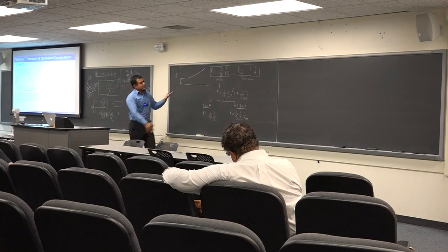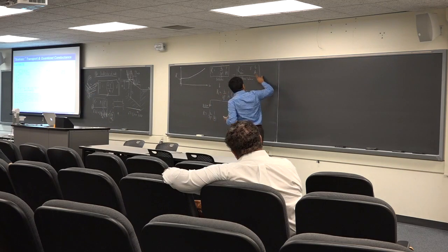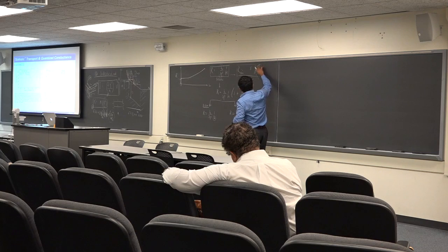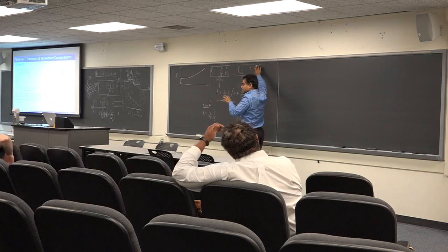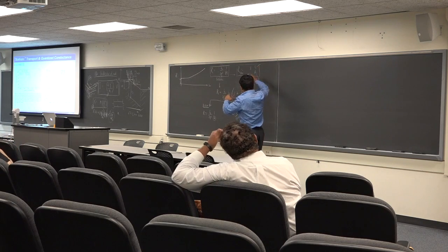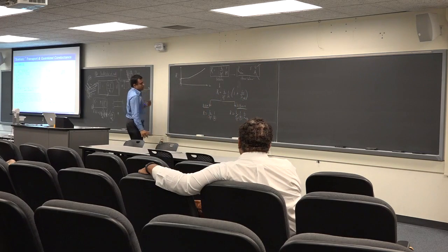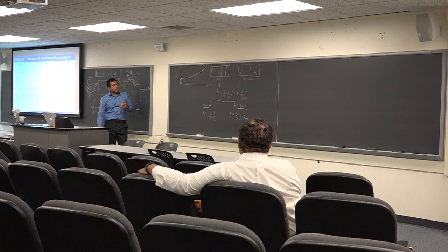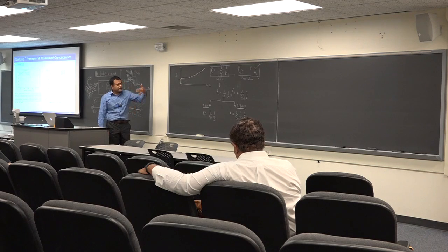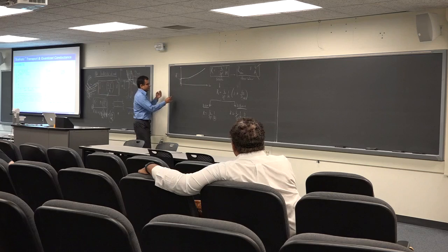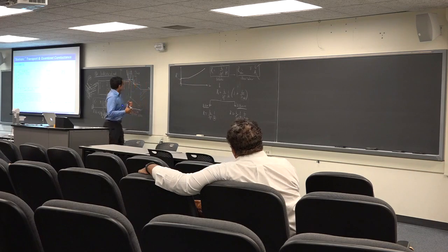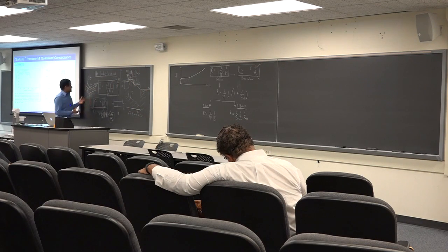If I look at it as a cross-sectional area and a length, then this is really not for a 1D conductor. This is for a 3-dimensional conductor, where we have a cross-sectional area and the length is L. So how do we think about the number of modes in a 3D conductor, or for any general conductor? Again, the number of modes is the number of waves that you can fit inside the physical dimension.